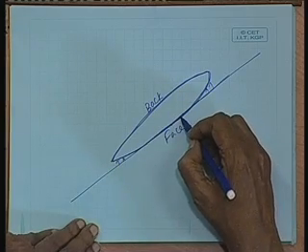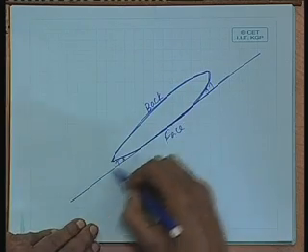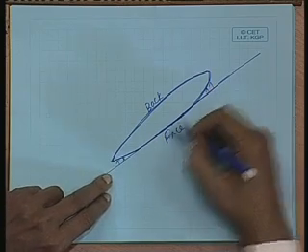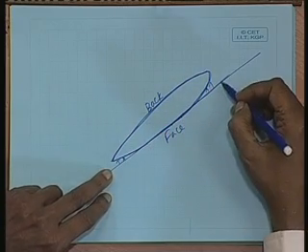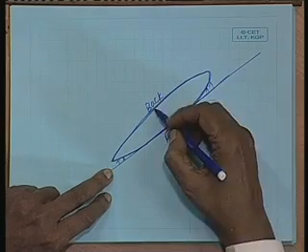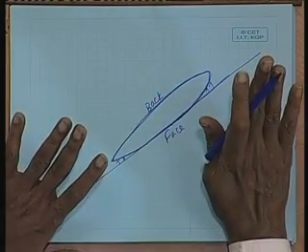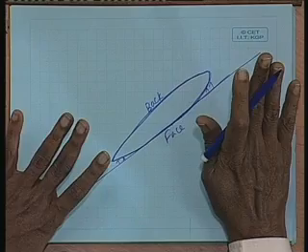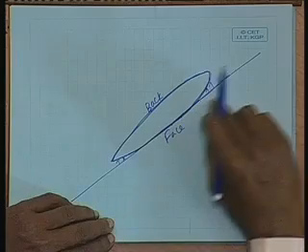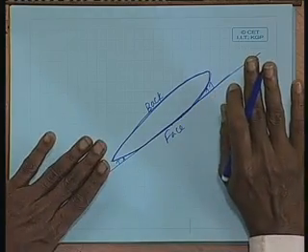This is supposed to be on the helicoidal surface, and you can see this is not strictly on the helicoidal surface, but slightly offset from the helix at the ends, that is at the leading edge and the trailing edge. The back is not on a helicoidal surface. We are not saying the same thing for the back. We are more concerned about the face, but it is more or less on a helicoidal surface. This is what we are trying to say.